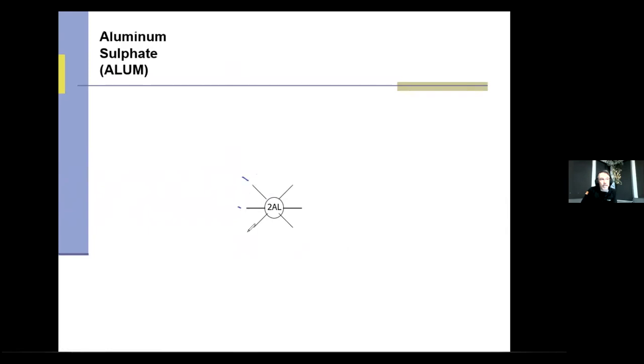So that's an OH. I'm going to need 6 of them. And these OHs come from the water. And they're going to go in and bond onto here. Now, this is alum. So you can imagine I need a lot of alkalinity to make this work. But I'll show you something really interesting. I'm going to put 3 of these guys back here. Hang on.